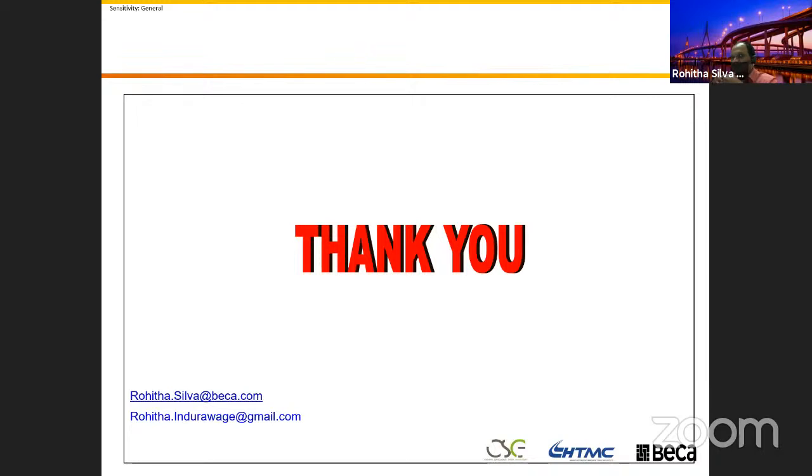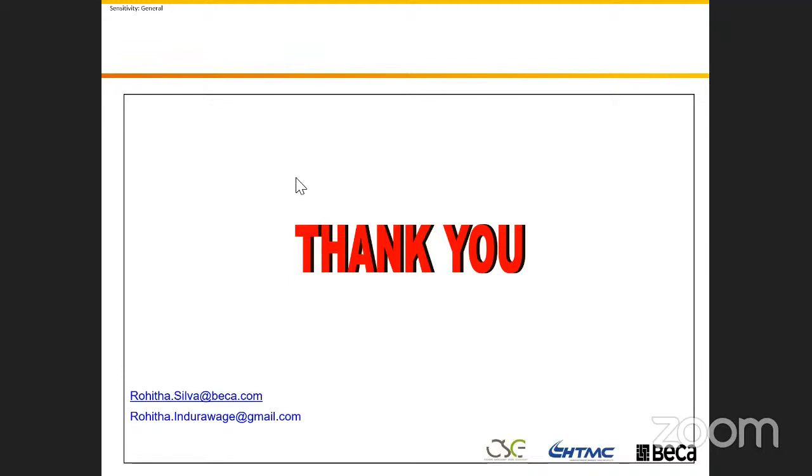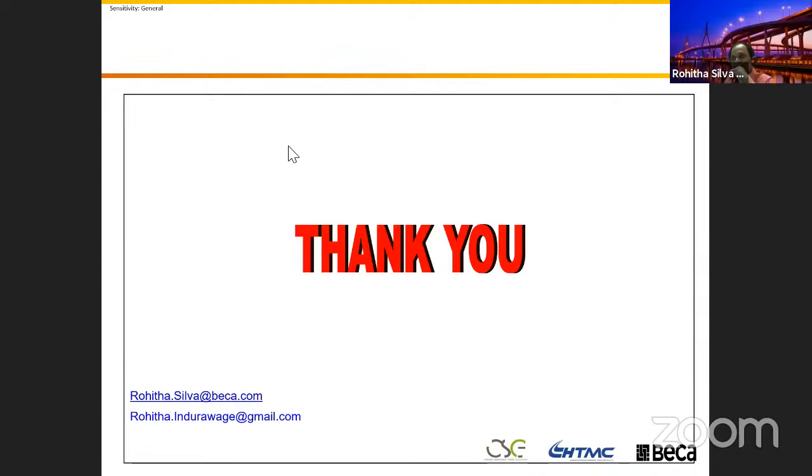I think I will share that one. It's L over 300, and when we check the deflection of the bridge, the whole bridge deck will be acting as a composite section. The deflection considers the whole bridge deformation, but the cantilever section itself is L over 300.